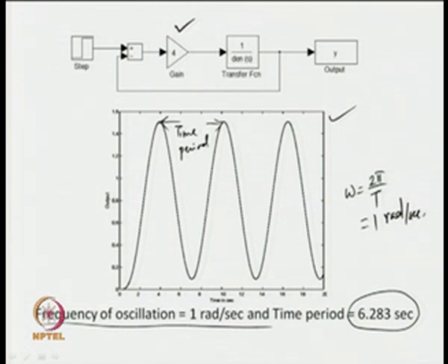Now, what benefit do we get from getting the output in this sustained oscillatory form? Now, we can make some measurements, like one measurement is the time period, another is the peak amplitude we get for this signal. So, one can measure the peak amplitude for this signal, and from there, suppose this is the baseline, then we will get the peak amplitude in the form of some A. Let A be the peak amplitude of the output.